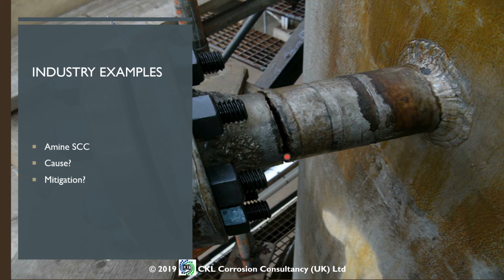Okay, so it's occurred along the toe where there are ample inherent stresses, close to yield in some cases, where the material is put under a great deal of internal strain and stress because of the welding operation as it tries to contract once it cools.